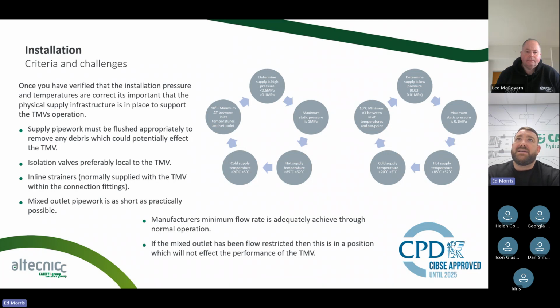The issue with that is if the flow is too low, the thermostatic mixing valve cannot shift the amount of mixed water out of its body quickly enough, and it will start to back up, which means that the mixed water we're trying to get rid of then sits in the body of the valve. It can't regulate its temperature properly, it gets confused. So we've always got to make sure that we've got a strong, good amount of flow leaving the valve, to offer it the best chance to perform when it's doing its thermostatic mixing. So just some things to consider when it comes to that.